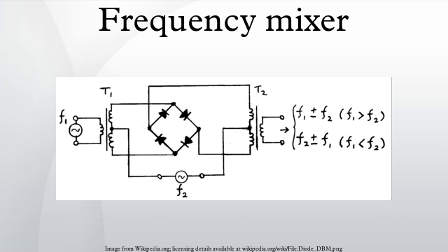Mixers may be built of discrete components, may be part of integrated circuits, or can be delivered as hybrid modules. Mixers may also be classified by their topology. Unbalanced mixers allow some of both input signals to pass through to the output. A single balanced mixer is arranged so that either the local oscillator or signal input is suppressed at the output, but not both. A double balanced mixer has symmetrical paths for both inputs, so that neither of the input signals appears, and only the product signal appears at the output.